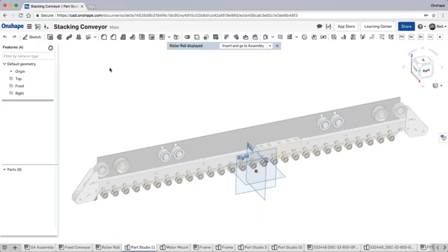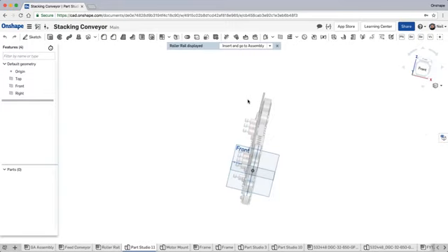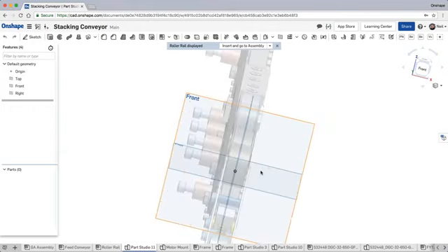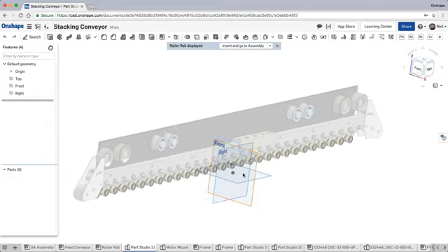What's also unique about Onshape and in-context editing is that it cannot be broken. In other words, in old CAD, if a file is missing or it's corrupt or it's maybe read-only or something like that, a reference can easily be lost and your assembly falls over. Because Onshape is entirely database and timestamp driven, this is the assembly as it appears at this point in time. And then if you need to make any changes, you can do that at a later date. Okay, so let's go ahead and make a belt.